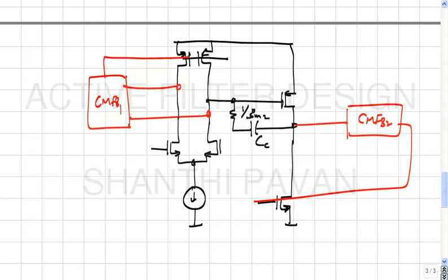So, the advantage of using a Miller compensated op amp is the really good utilization of the possible supply swing. You are not throwing it away and wasting the supply on a whole bunch of transistors that are not doing any work. You lose only the bare minimum needed.